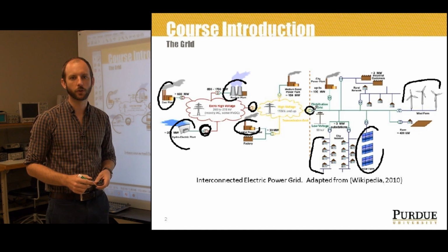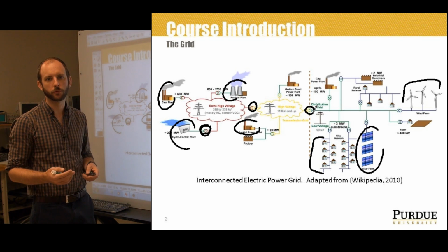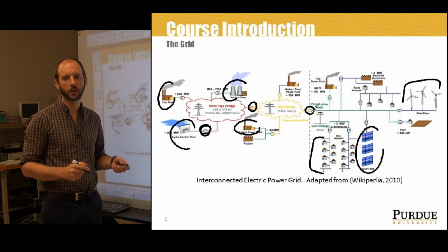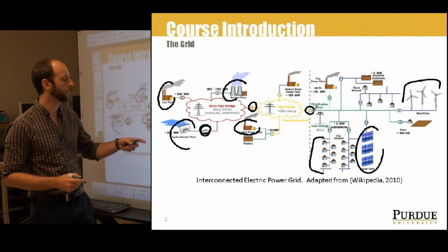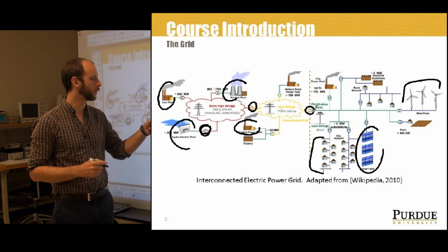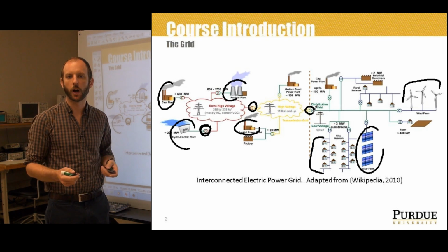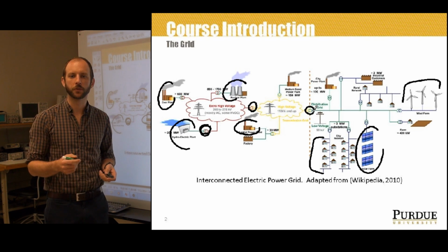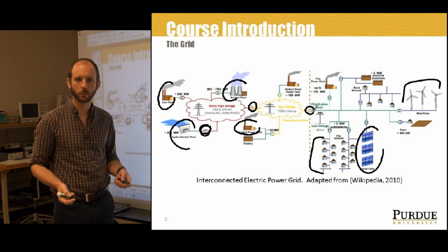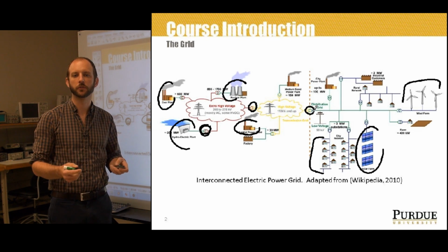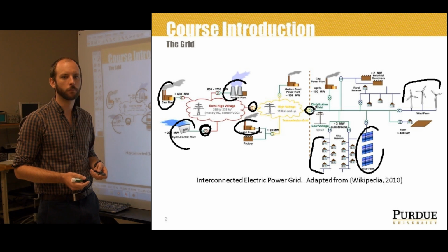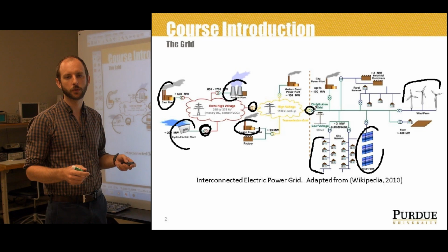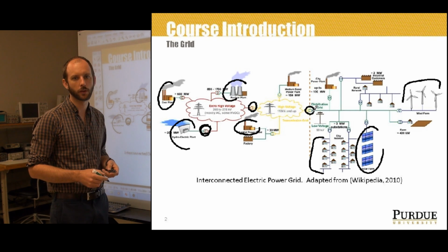And the purpose of that is to reduce the distribution voltage, the voltage that's seen on the conductors in the distribution system, in populated areas down to like 4 to 35 kilovolts, so that it just has less risk of shock. It won't be as dangerous of a situation, right? Because these cables are near homes, near businesses, near trees and things like that. They run over your roads, so having them at lower voltages is just safer for all of us. They're also a little easier to work with if they're lower voltage. So it's stepped down, like I said, to between 4 and 35 kilovolts for distribution levels.